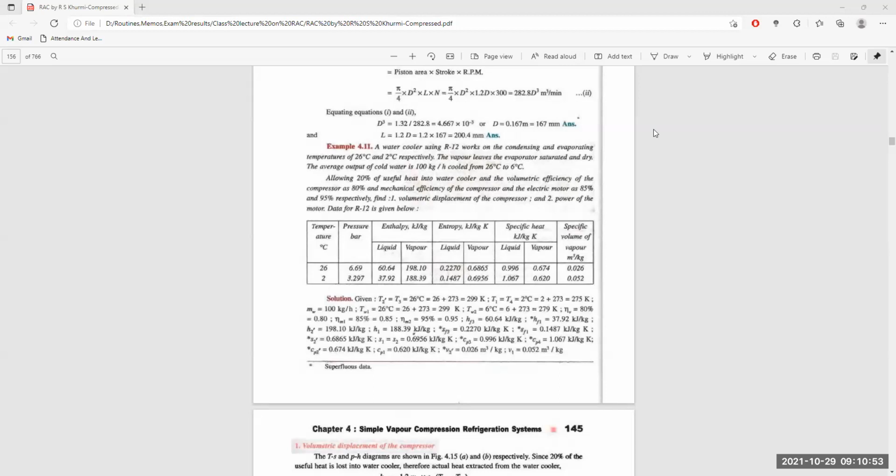We are discussing, first of all, the vapor compression refrigeration system with various variations of the different stages of the refrigeration system. At present, we are discussing this in such a way that our compression process is the beginning. The compression process starts from the vapor saturation line. That is, stage number 1 is situated on the vapor saturation line.